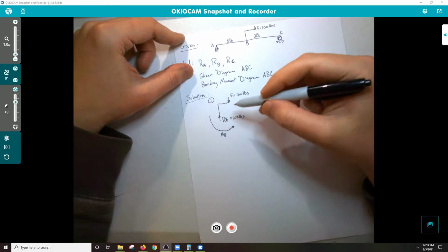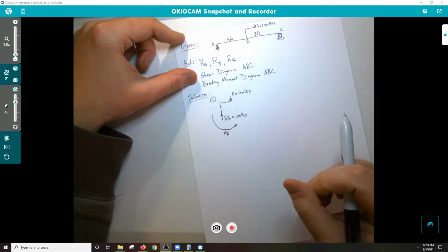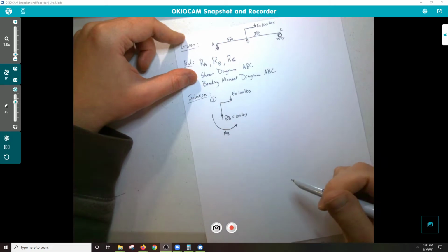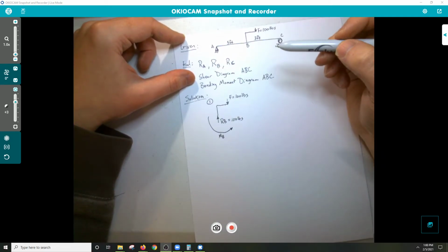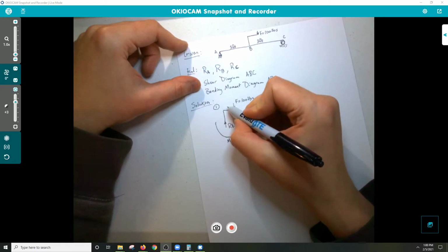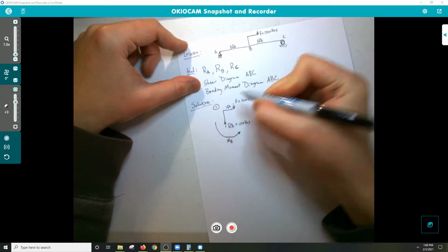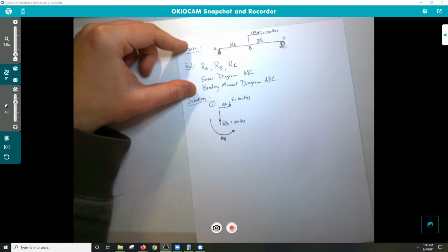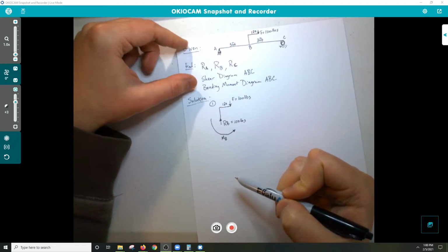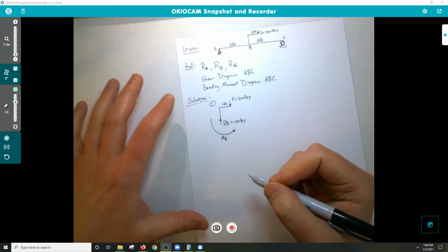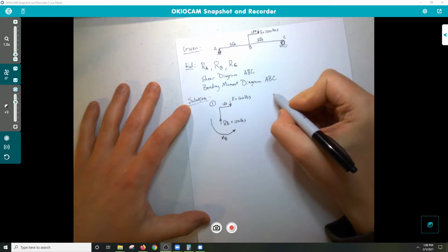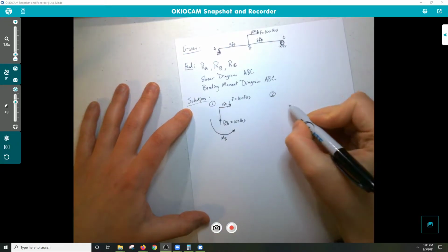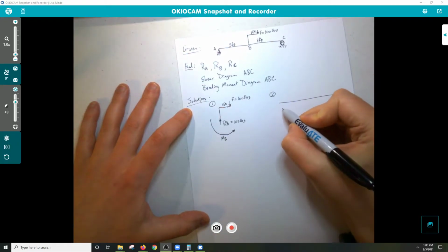And we can actually calculate. We'll see that if you weren't sure, for instance, what that moment is or which direction, you can actually use your equilibrium equations to help you with that. So I'll explain that here in a minute. To do so, I realized I forgot one other measurement here. So we have to have that 1 foot in order to be able to figure out what this moment is, right? All right, so first thing again I do after I get my free body diagrams drawn is I go through equilibrium equations. And I think I should probably finish drawing out my free body diagrams here.